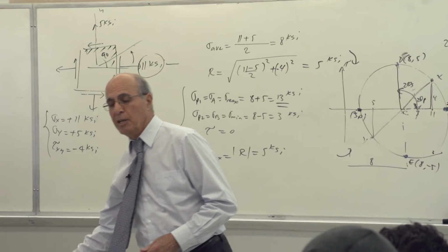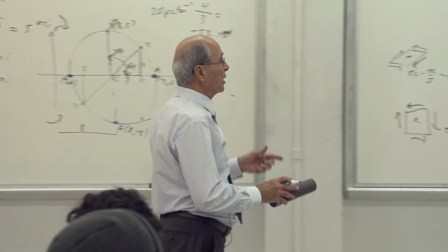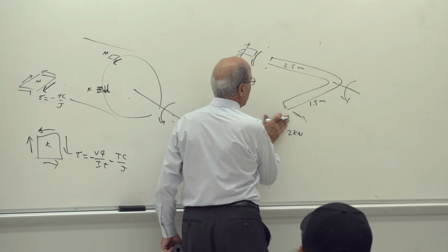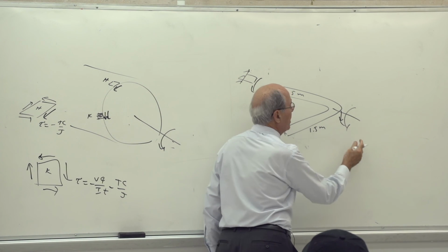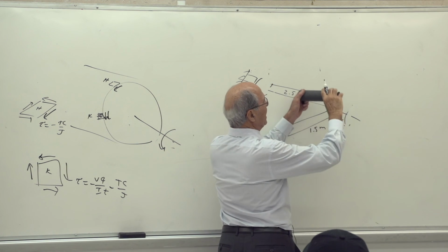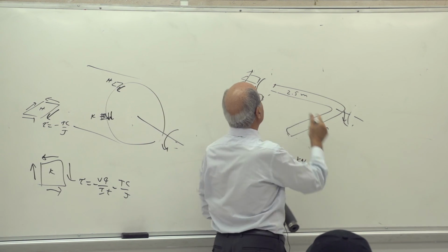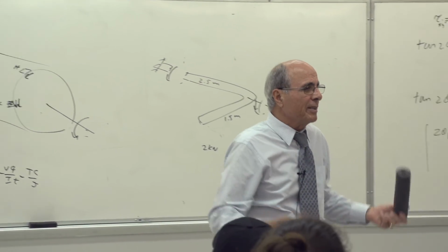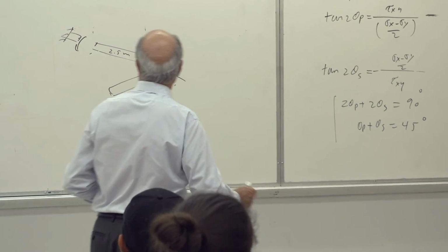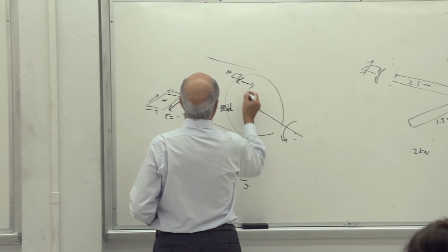All I'm saying is, what happened here, if you're making a mistake, is this load first comes here and becomes a force and a torque. But when it is hanging at that end, it's going to bend like that. So on the top, you get tension. In the middle, you get nothing. On the bottom, you get compression. So on the top, you get a tension like that.